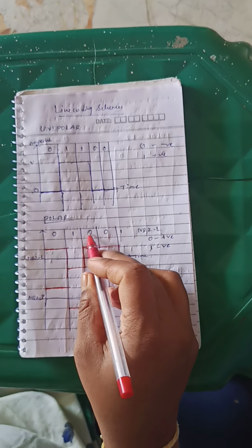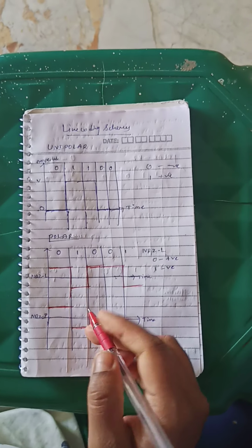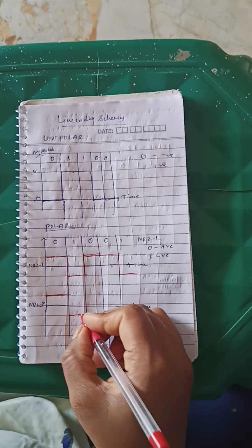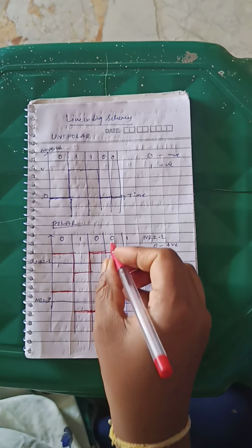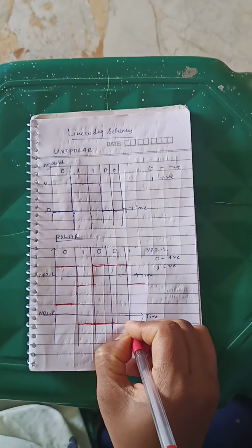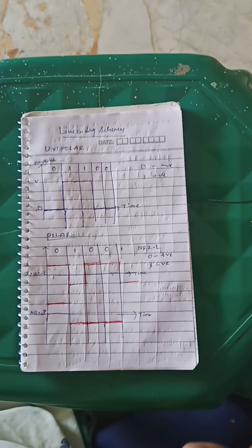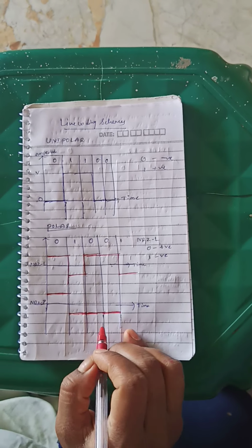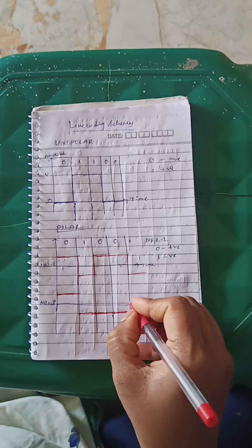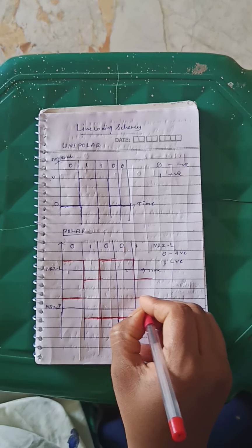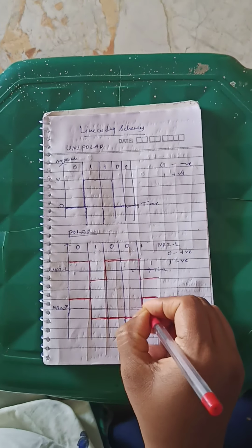If the next bit is a 0, it is going to follow the previous bit output. The previous bit output was 1, so it is negative, and it is going to follow the previous bit output, so now it becomes negative. Again if it is 0, yes, it follows the previous bit output, that is negative. Until the next bit is 1, it is not changing the timing diagram. So it is always following the previous bit output. Again the final bit is a 1, so now it is going to change the signal to positive. So finally we have to join all together, so we will get the output.